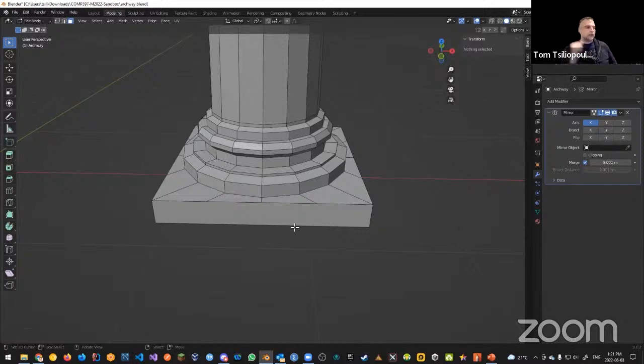Is there a problem, guys? What is the problem with this structure that I put together? The problem is, if we ever want to UV unwrap this thing, then we're going to have an n-gon right here. An n-gon, and it's spelled like this, n-gon. An n-gon is a polygon that has multiple vertices, but one big face. It doesn't make any sense.